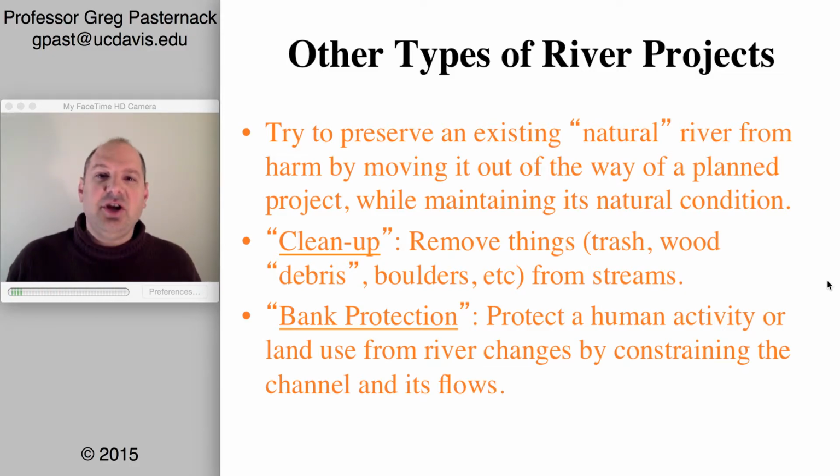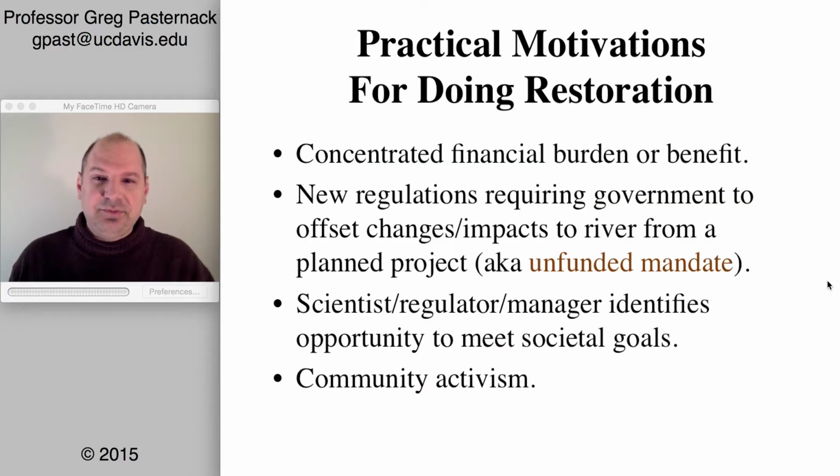Bank protection is often cited as a river restoration action, but it's the exact opposite of it. Banks naturally collapse. However, there are times when rivers have become destabilized, and then you may have excessive or inappropriate bank failure, but that doesn't mean that bank stabilization is in and of itself a form of river restoration. It's just a defensive action that people have to take.